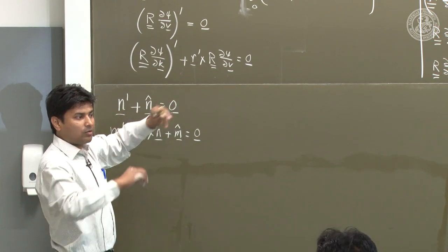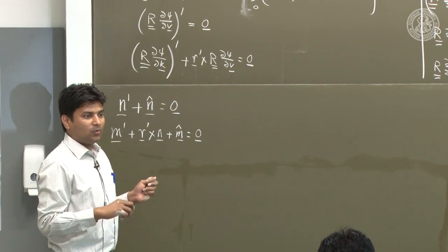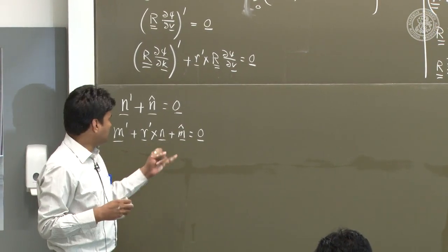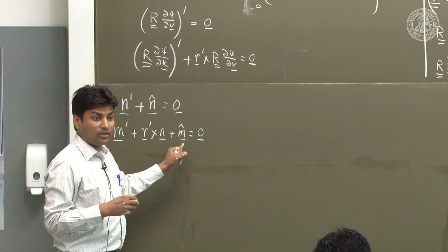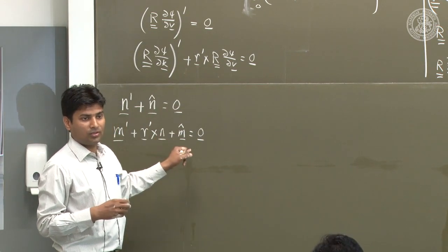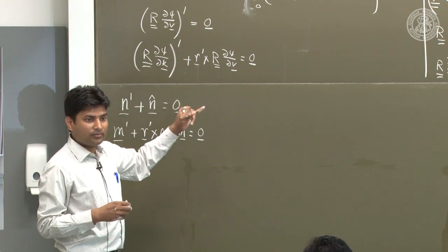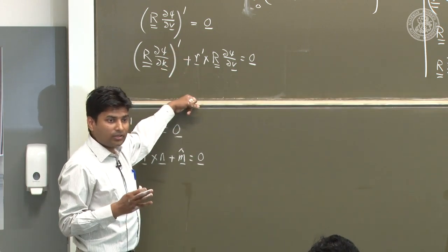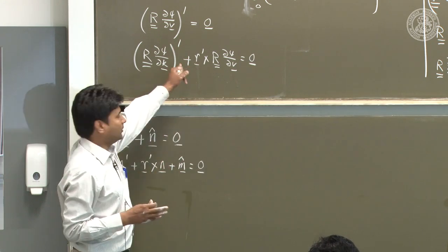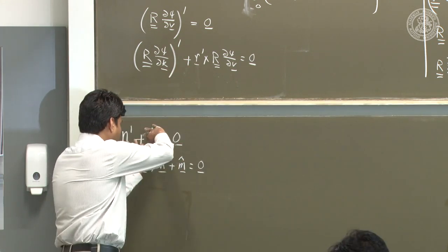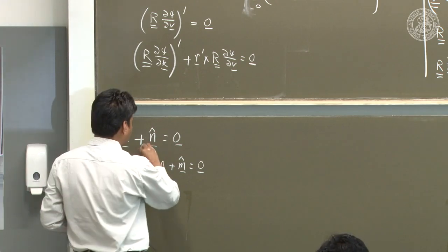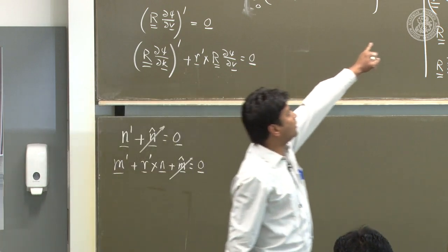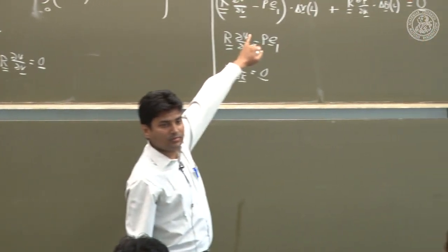Because in our potential energy, we had not taken that into account. These are due to external loads, right? We did not take the potential of these external loads. If you had taken them, then you would have gotten the extra terms there. But since you did not take it, they did not show up here. So let us forget about them. They are not present because we did not consider it in our cantilever problem. There is no distributed load or couple, right? So it did not come there.